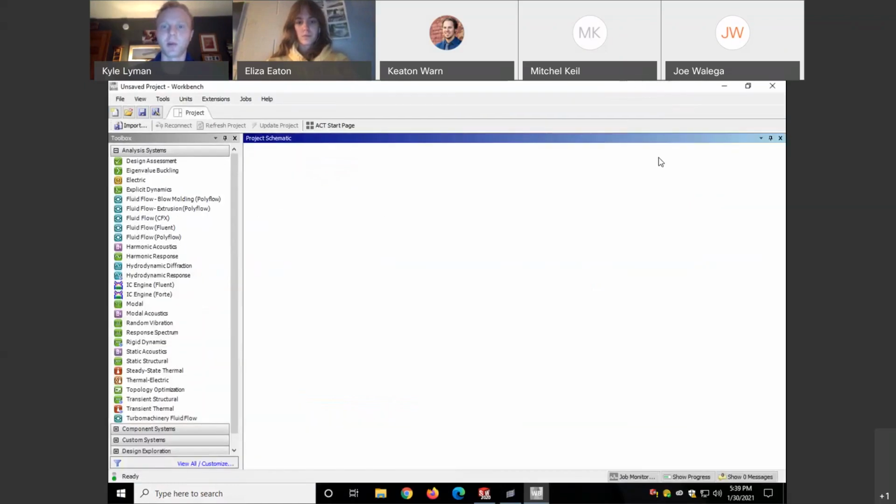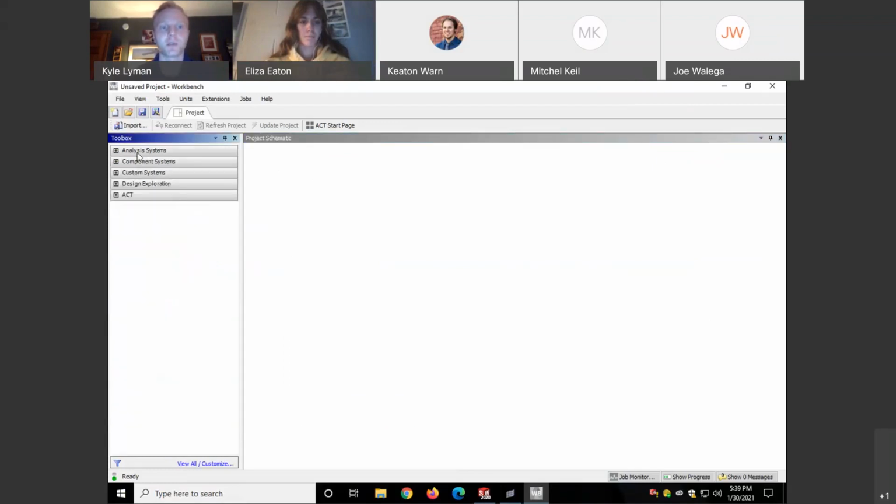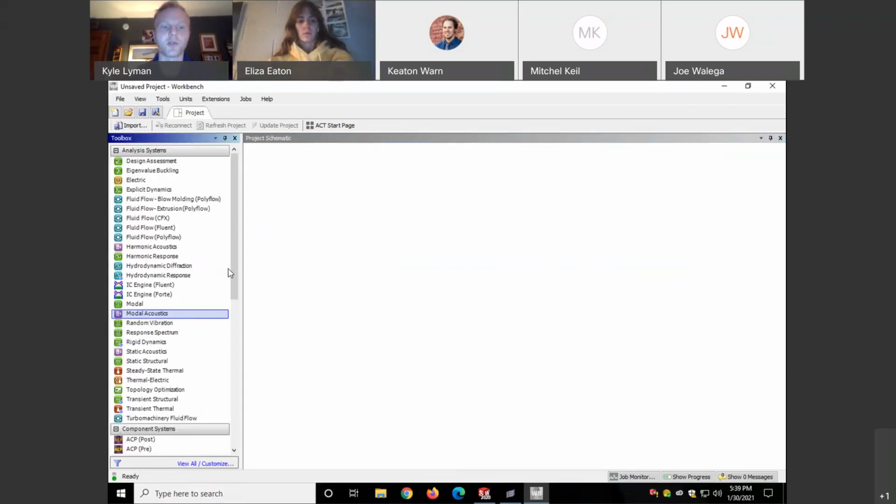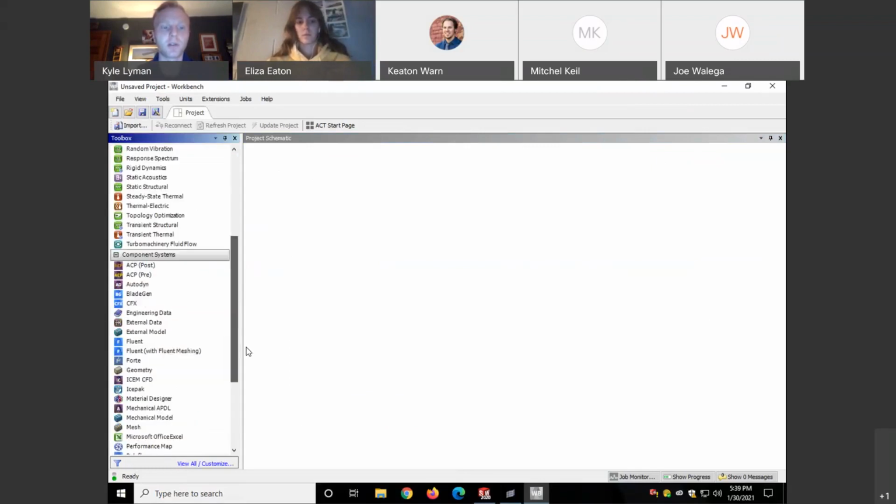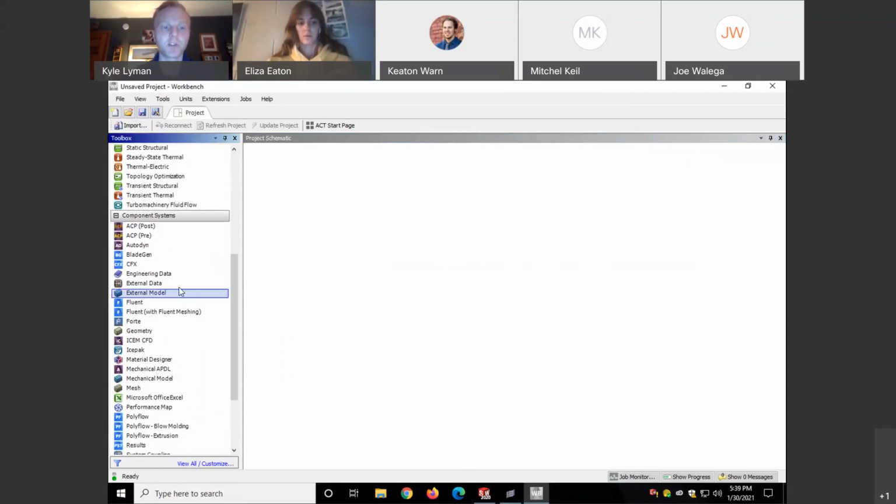Now we are at the Workbench homepage, and if you've watched my other video on the ANSYS tutorial, you probably recognize this. If you haven't, make sure to check it out. It'll help out with understanding what you're looking at. But a brief explanation, you have different things in your toolbox here. So you've got analysis systems, component systems, customs, and so on. I expand the first two, analysis and component, because that's what I usually use. So under component, you're going to see one called external model. You're going to left click on that and just drag it right into the screen here, create standalone system. And you can see that this box has popped up here.